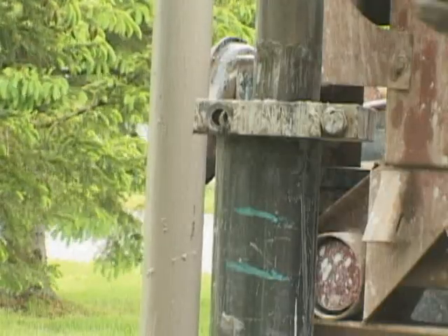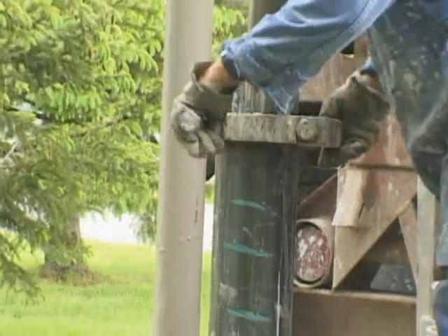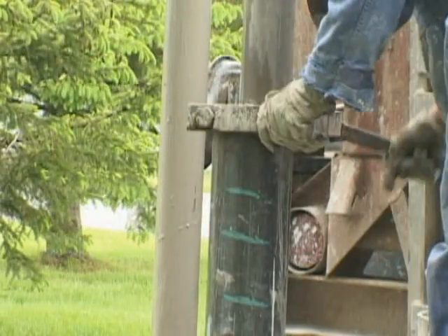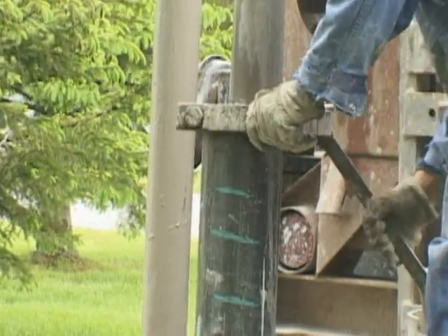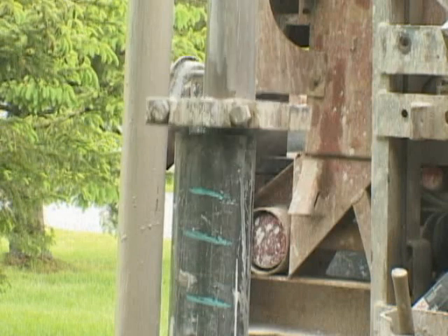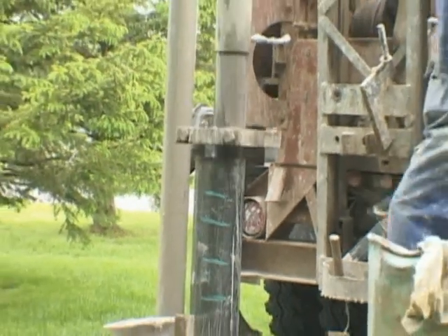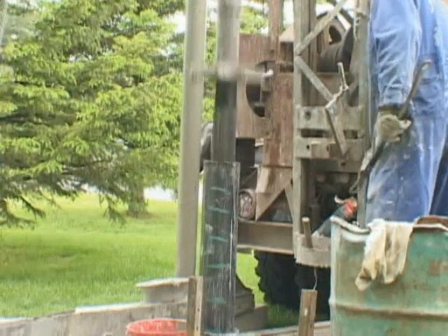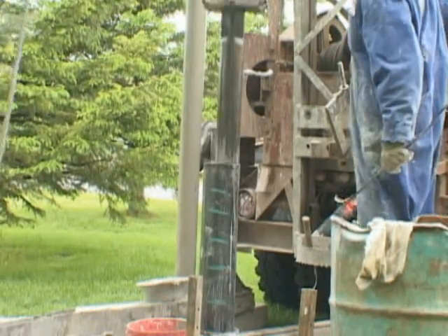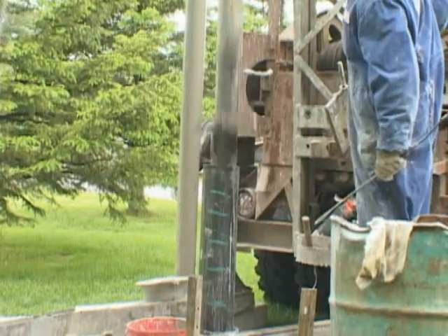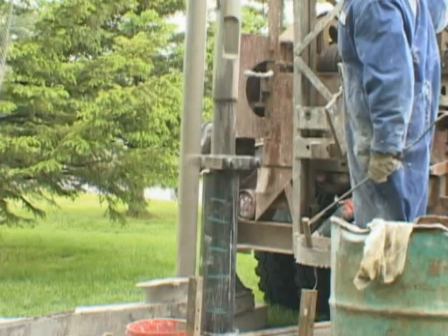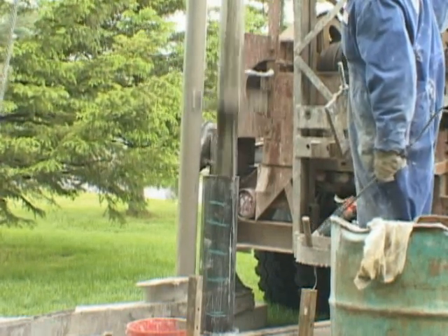The drive blocks then enable more energy to be transferred to assist with driving the casing down. The casing advancement continues in overburdened situations until such time as a suitable aquifer is encountered, or until the casing is firmly seated in bedrock, after which casing is no longer required, as the geology itself, or rock, stabilizes the hole.